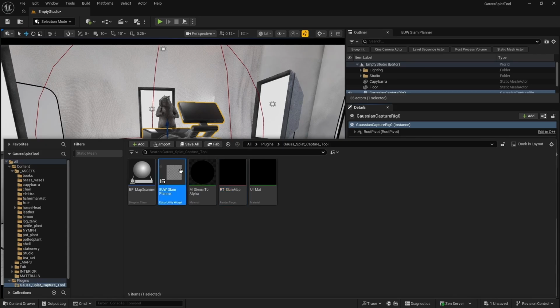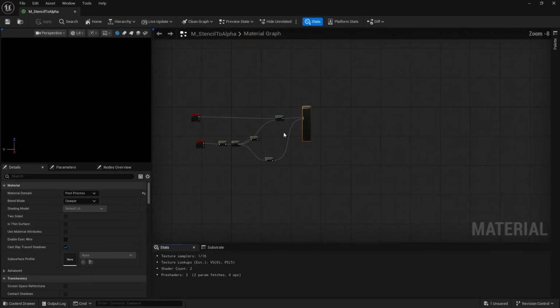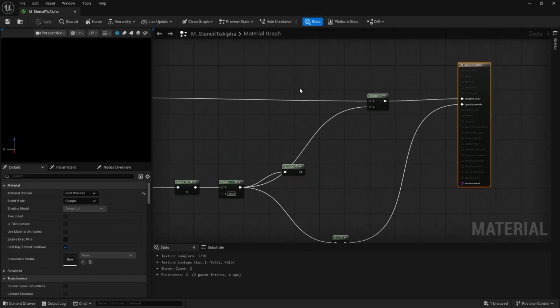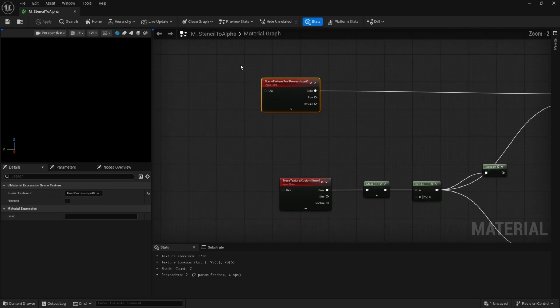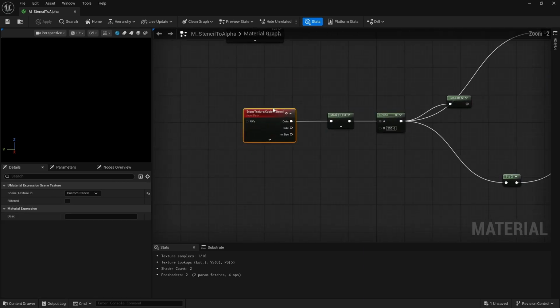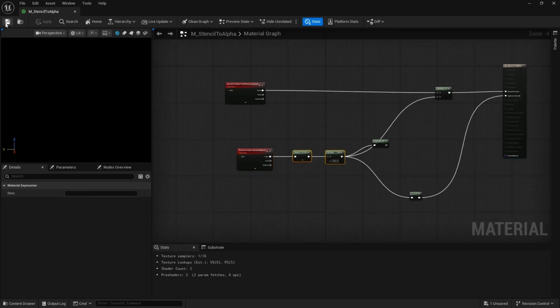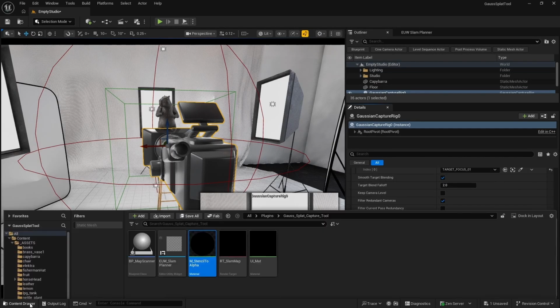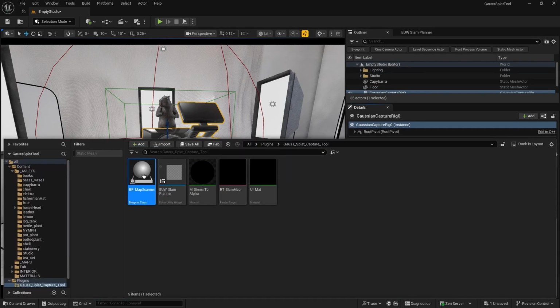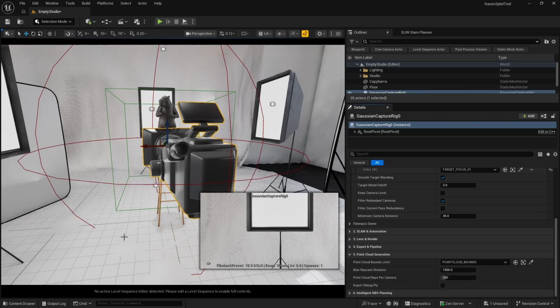The planner, this is for the visual planner. I'll take you through that. The stencil, this material just handles the masking. If you go inside the material, it's a quick post-process material that essentially just cuts out the alpha for the selected or tagged objects. And then we have a 2D capture component for the slammer method. I'll show you when we get there. And then it's just render targets for the shader. And the quick setup just sets these things up for you.